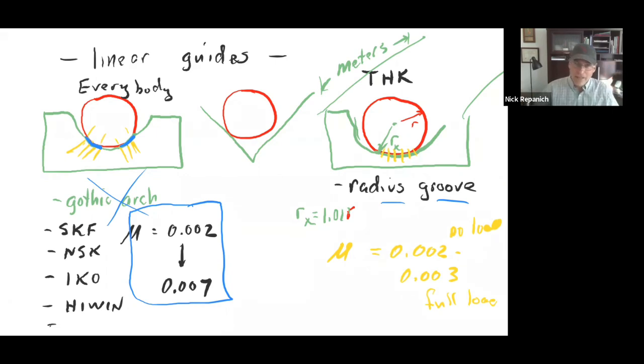And the way they did it is, just like how they pick precision resistors, you make the best machine you can, and then you make parts on it, and then you take the parts off that machine, put them in the machine, and make more parts. And those parts are better because you took the very best linear bearings that you made and put those in the machine that was making linear bearings and made more linear bearings.